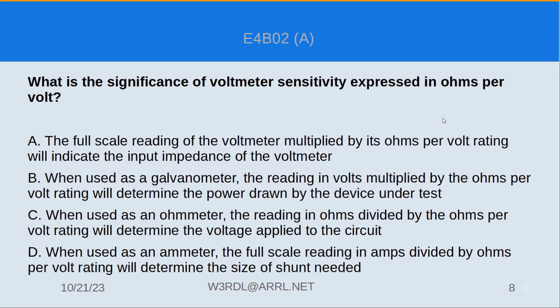So where would that really come into play when you're taking a resistance measurement or something? Voltage measurement? Because on a resistance measurement, well, maybe a little bit, but you're actually sending a current and measuring the voltage drop. So, you know, it's a generator. But you do have a parallel impedance when you do that, so I'm sure it would affect it some. So you'd want that to be a higher impedance.